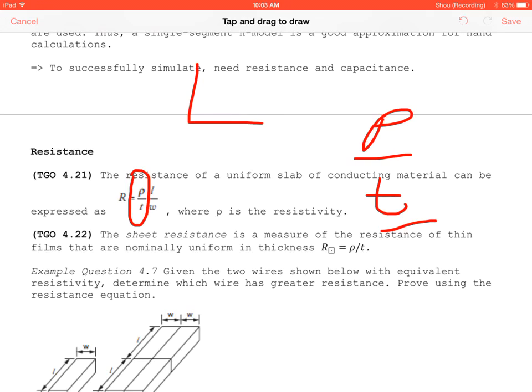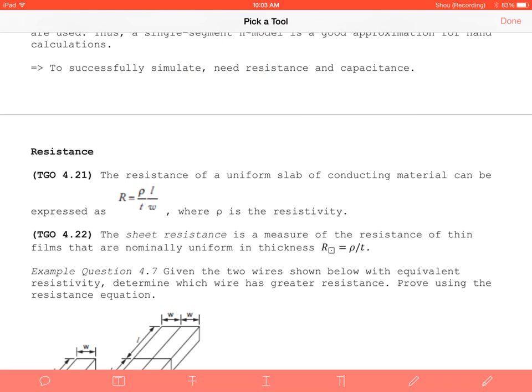So you have your length, you have your width, and you have your dielectric underneath. And as we saw from the previous picture, those dielectrics become important because that's the difference between metal wires next to each other. So we're going to have wires on top and below each other, and then wires next to each other. Regulating that distance allows us to regulate power consumption in the circuit.